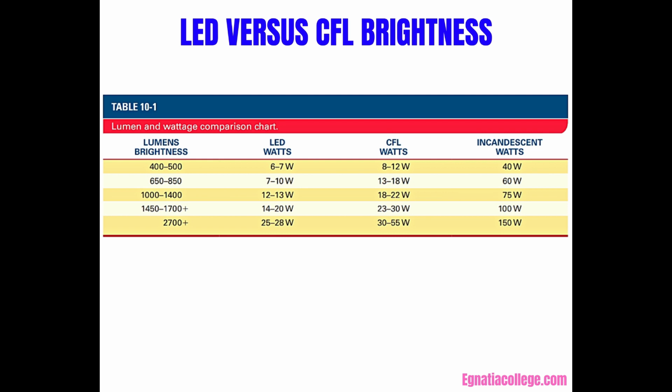When mercury gas gives off light, it is ultraviolet light that the human eye cannot see. To turn the light into visible light, a coating of phosphor is deposited on the inside of the glass tube. Phosphor glows white when struck with UV light, and this is what fluorescent light is. LED lighting uses semiconductor technology to make light without the requirement of heat as a precursor.